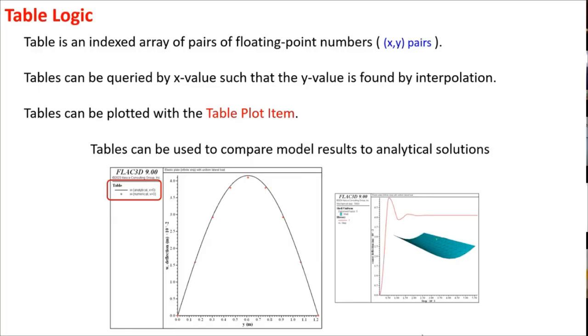So for example, I did a bunch of work in FLAC3D to have shell structures. So here's a shell structure with pressure on the top, loaded with the two sides sitting there, can't move. So it's the bending, right? And this is the deflection at the center. And so we're plotting deflection versus step number. And eventually after the pressure equalizes, the deflection stays the same.